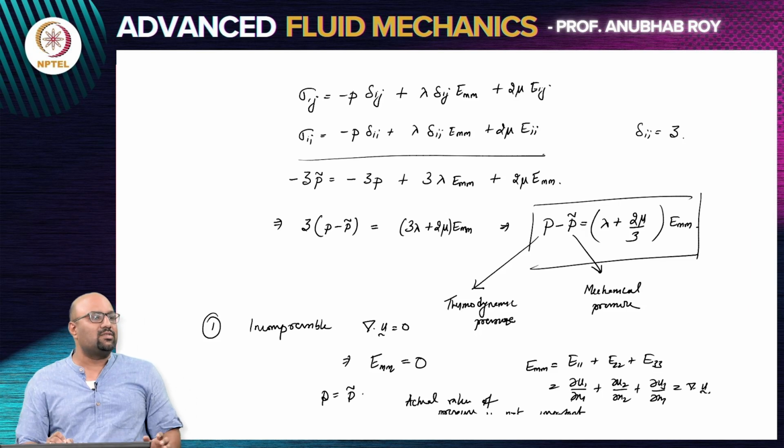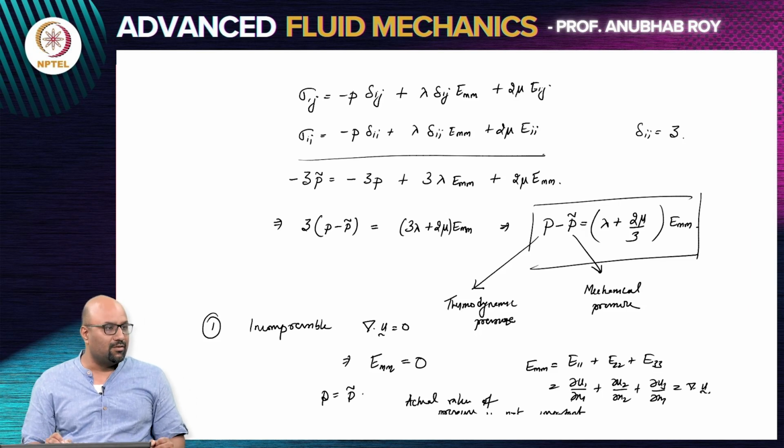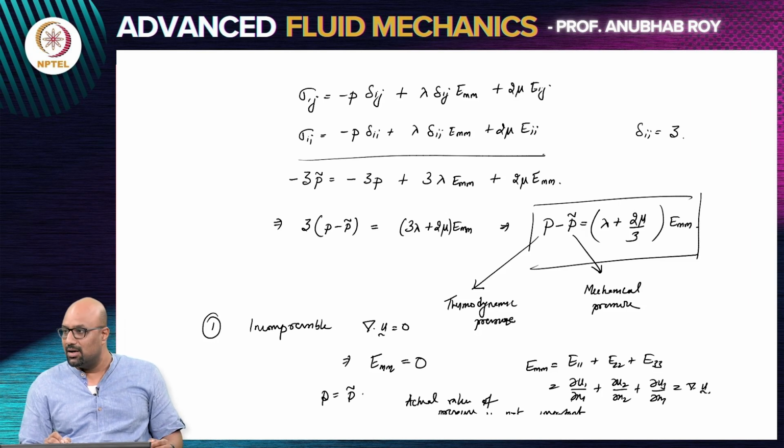What is the precise value of pressure is no longer of any significance. Now, all that you basically will care about is the pressure gradients rather than the precise value, because you have arrived at a relation that your thermodynamic pressure is basically going to be the same as your mechanical pressure, which is nothing but the mean normal stress in the problem. So, the precise value does not matter because the system is driven by gradients in the stress.